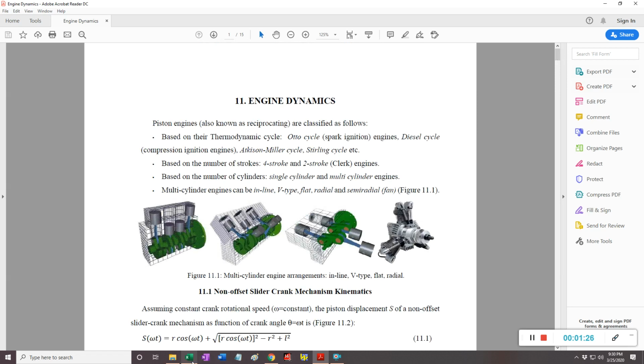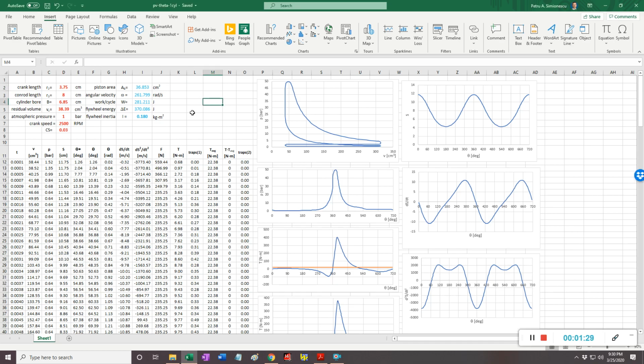Okay, now for the spreadsheet, the startup values are the digitized PV curve. The time column is generated later, sorry for the background noise, once you get the contiguous theta produced. And as you can see, it uses omega, the angular velocity, knowing the RPM of the crank.